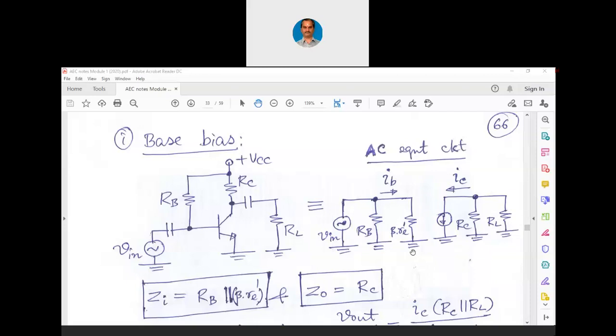Ideally, any amplifier should contain very high input impedance, which means what? When there is very high input impedance, the signal can be very less in amplitude. This very high input impedance simply means that the circuit will not take much current from the input signal itself.